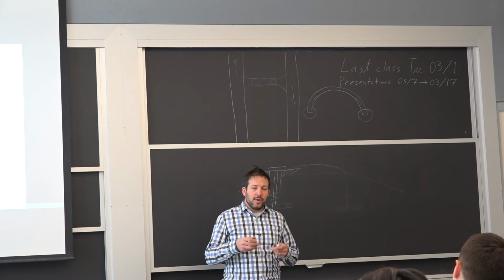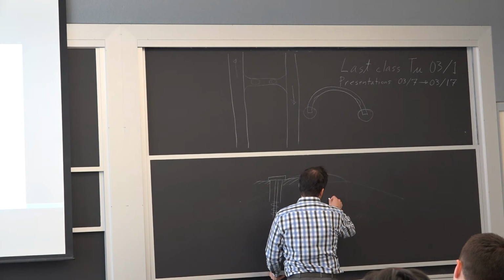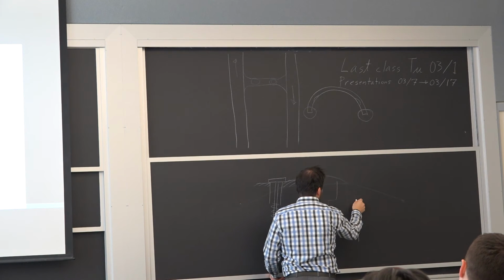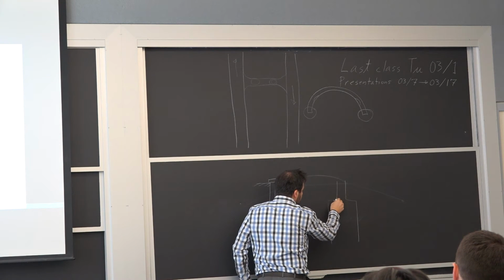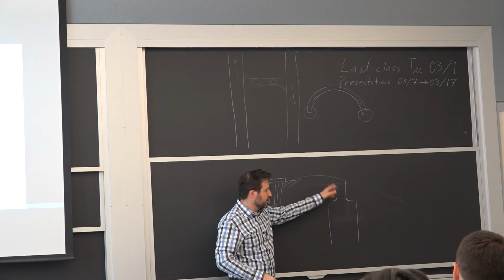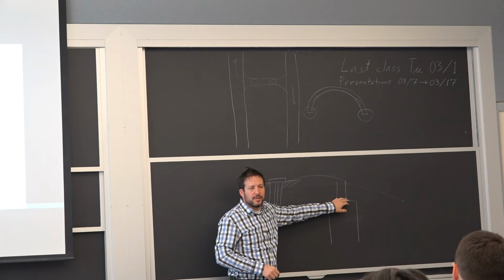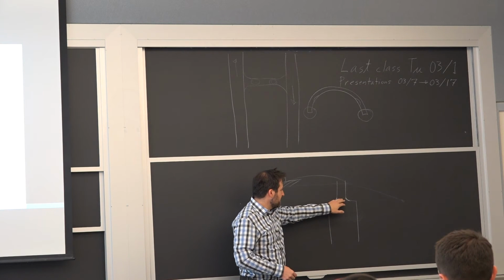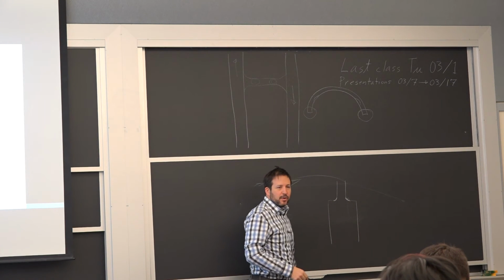It will matter if you have a very detailed machine part, and maybe I'll illustrate it in a slightly different way. Let's say you have a shaft that needs a little reducer in it, so you're looking at something like this. The roughness, in the sense of how smooth this radius here is, is very, very critical. I've seen it too many times that people will put a design together and don't specify exactly what they want in these corners. You can't imagine how many times I've seen it.